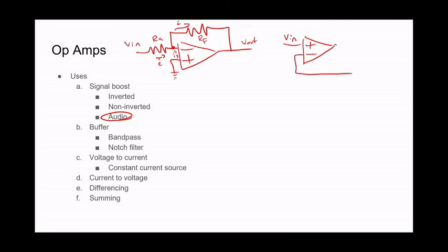All right, now we're going to have the positive side on top with our Vn right here, and we're going to have our negative connected to our output via a voltage divider. So we have our output here, and we're going to have R1 and R2. Now, if you remember from our previous videos, and using rule number 2, we know that this is Vn. From our previous video when we talked about voltage dividers, we know that Vin, in this case, equals Vout times R2 over R1 plus R2.